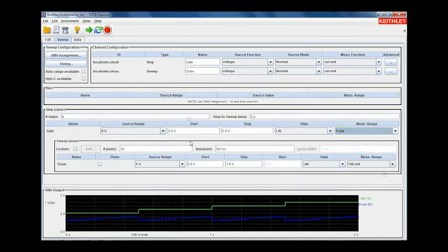We again have to go to the 6 volt range on the drain, as I want to sweep from 0 to 5 volts in 0.1 volt steps. So that'll yield 51 total points here. And the measurement range at 100 milliamps is correct because we will be setting a compliance limit of 50 milliamps, so that's appropriate here. Now let's hit the green run button, which is the arrow up at top here.